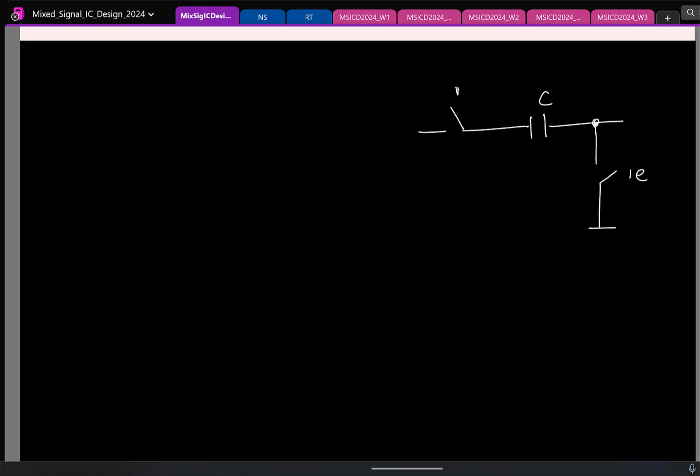Of course, this is not the only way to tackle charge injection. In your practice set, I'll give you a couple of other techniques you can use, but unlike most of them, this is a one shot way to eliminate signal dependent charge injection, because we are essentially making this impedance open, so nothing should ideally flow. But then we noted that in practice there can be a small off capacitance. So let's say I draw it like this. Because of this, this impedance will no longer be infinity. It will be finite but still a large number. So the charge injected from here will not be exactly 0. So you can still have some signal dependent charge.